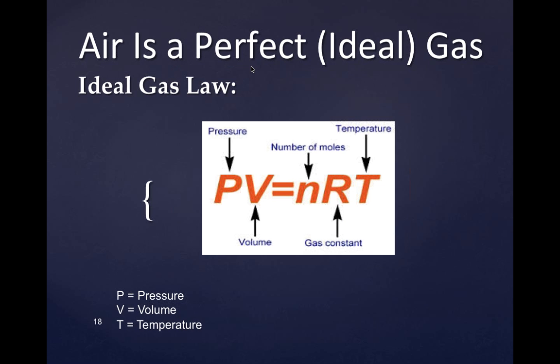During the week, when you read these questions on the exam, I hope you're going to have an easier time with them. Some of these are obvious, right? When you have a contaminant that's heated, for instance, the warm air is going to rise. So with a canopy hood, you're putting the hood above the process because you expect the contaminant to go that direction, and you want to control it from escaping somewhere else.